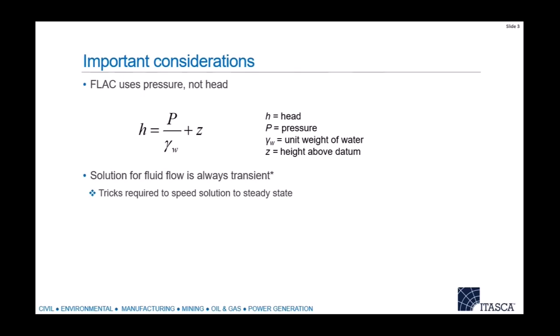Also, another little side note: compressive stresses are negative, so negative values are compressive. That's not true with pore pressures. Positive pore pressures are compressive. A little bit inconsistent, but that's just the standard we use, okay? So positive pore pressure is compressive. A negative stress is compressive. For now, this is not true in the upcoming version.